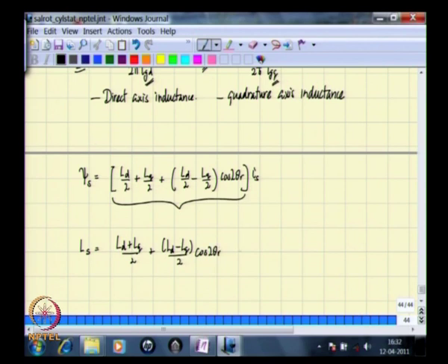Note that in the inductance expression we have derived, what we are essentially determining is the flux linkage, and in determining the flux linkage we are assuming that the MMF generated by the stator produces flux which crosses the air gap and goes into the rotor, and therefore all of this flux would link in some manner coils that might be on the rotor.